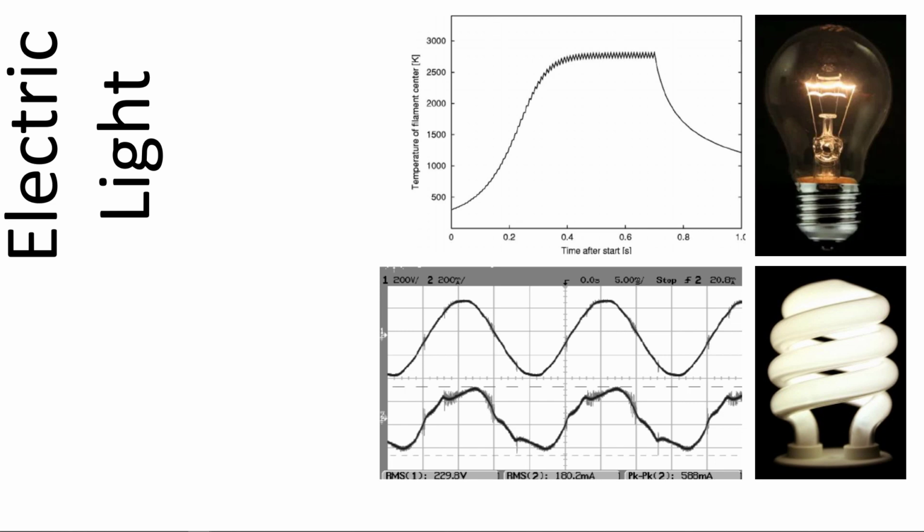So a standard fluorescent bulb puts out 120 pulses of light per second. Your eye can't see it because of persistence of vision. Now, if you weren't really aware of that and you started working with vision systems, that means digital cameras, and you started to do, say, snapshots, and you took a series of images, you would find some of them light, some of them dark, and some of them somewhere in between, because the charge coupled device, the CCD in the digital camera, can respond at that high frequency because it does not have persistence of vision.